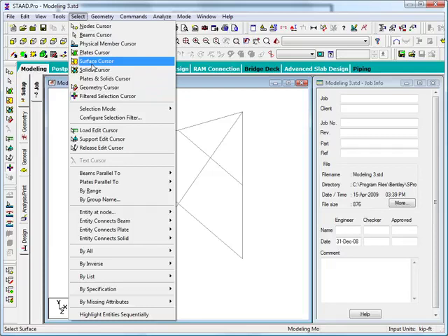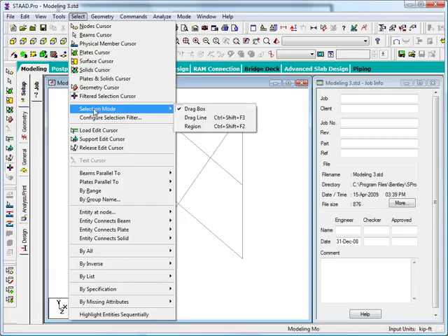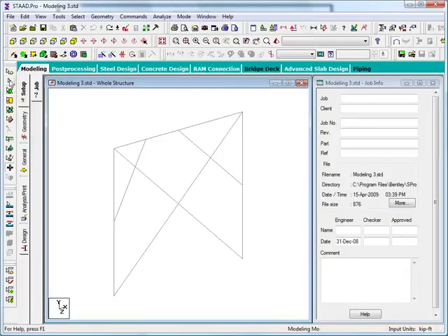And then where the choice of the cursor controls what you're going to select, there's also a related setting here called Cursor Selection Modes that controls how that cursor will select. So let's just start with our basic beams cursor and show that we can click, or we can press and hold Control and click to get multiples, or click once to deselect, and now click and hold down and stretch, and notice that I'm making a rectangular fence.